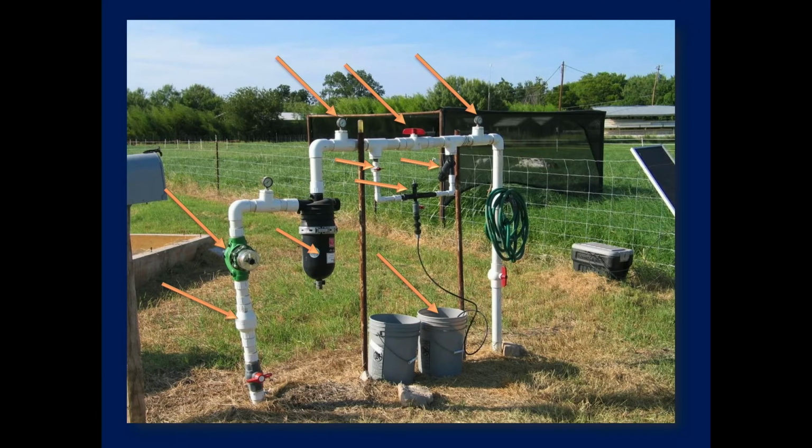Now, some counties, if you're on county or city water, may have specific regulations saying you've got to have double check valves or some other combination of things. But basically, all this does is prevent fertilizer flowing backwards into your well. I have seen that happen. I've seen wells come out with blue water because they accidentally injected, everything reversed itself, and you pulled the fertilizer right back into the well. And blue water does not taste good.